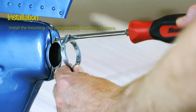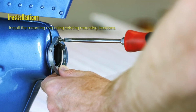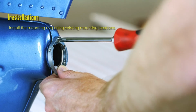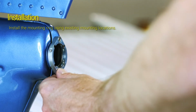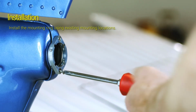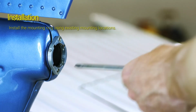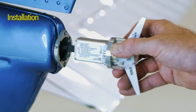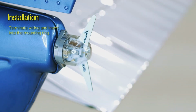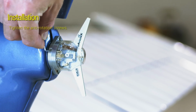Install the mounting ring using existing mounting locations. Terminate the wiring and insert the tailBeaconX into the mounting ring. Tighten the anti-rotation screws.